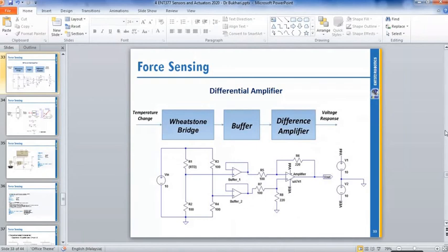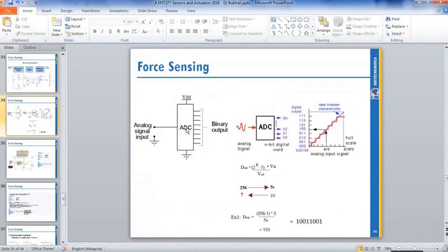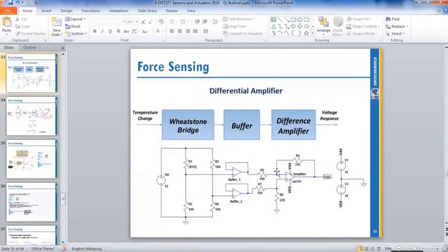Okay, so this is still analog. It's not digital yet. The output here is still a sine wave, and a sine wave is not digital. Then we need another circuit we call ADC, analog to digital converter. After you increase your signal 10 times, with this RF and this R1, 0.01 becomes 0.1 volt.